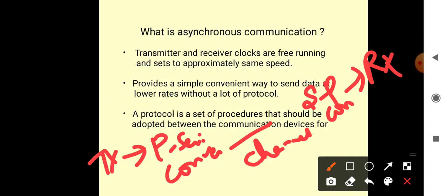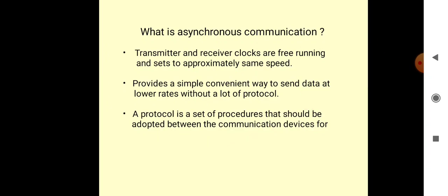So in order to avoid that, if you use a parallel to serial converter, you can directly take one wire to communicate these 8 bits. This is nothing but the parallel to serial converter, which will be maintained at the transmitter part, and the information is given through the channel. At the receiving end, again the serial signal will be converted into parallel. That is, you will use a serial to parallel converter, and then you have the receiver. So in this way the data will be communicated.